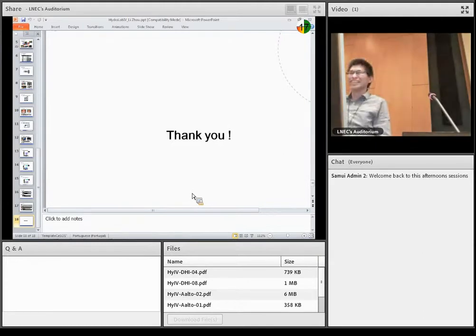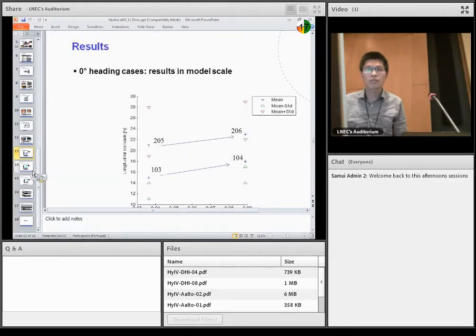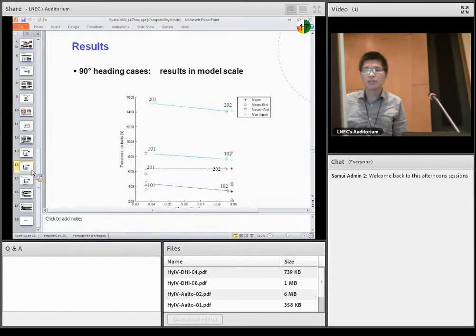Okay, do we have any other questions? Yes, Mark. Mark Rijnbreteler of Deltares. It's not really my topic, so perhaps this is a very stupid question, but what I saw in your test results is that you have a mean value here on the hull of the ship and quite a large standard deviation. Still you had a very nice homogeneous ice sheet. I can imagine that in reality the ice sheet is much less homogeneous, giving an even larger standard deviation of your forces. How do you cope with that variation of forces?